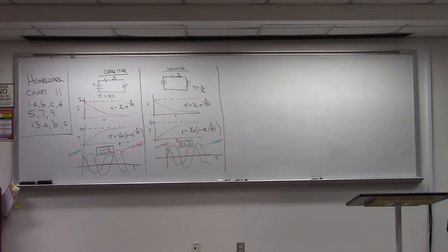So one of those is voltage and current on the capacitor, and one of those is voltage and current on the inductor. Let's see your circuit. Look at this. So here's your current probe. The voltage across the capacitor is the red. The voltage across the inductor is the green, and the current through the inductor is the yellow. So that's how you can tell. Okay?